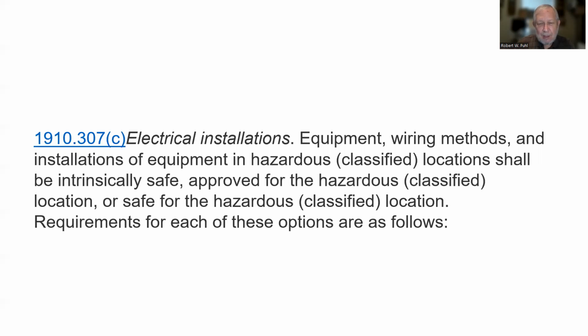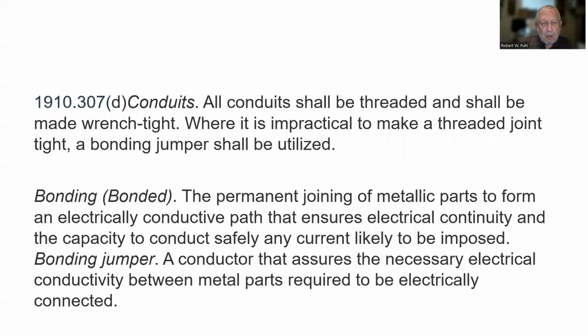I don't know why they just don't tell you that they're going to call it one thing instead of saying hazardous classified throughout. Conduits, all conduits shall be threaded and shall be made wrench tight, that where it is impractical to make a threaded joint tight, a bonding jumper shall be utilized.